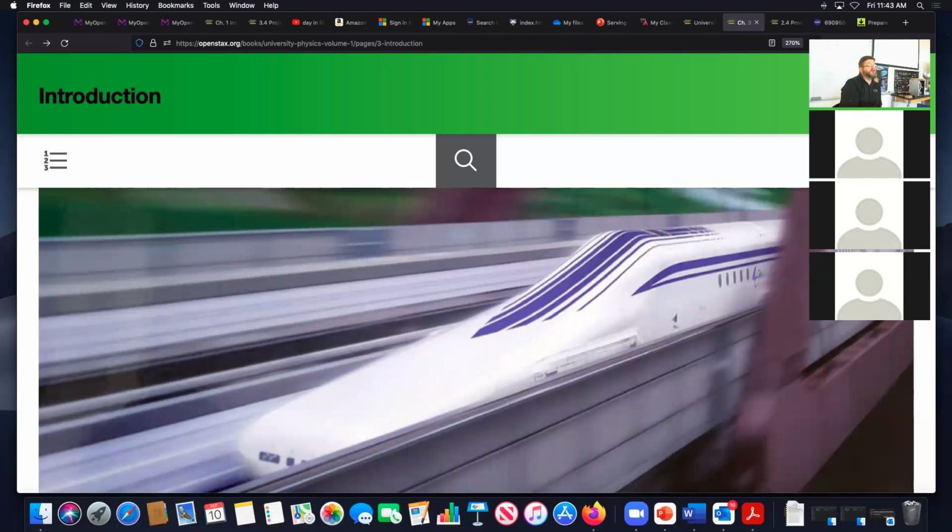And that creates a huge current in the aluminum, which creates a magnetic field, which opposes the magnetic field in the superconductors. And we have two opposing magnetic fields, one from the train and one from the track. They're going to push on each other, and the train floats above the track. But it only works if the train is moving. So when the train is not moving, when it's in the station, it actually falls down to the tracks. And they put wheels on the bottom of the train so that when it slows down and it gets closer and closer to the tracks, it can land.